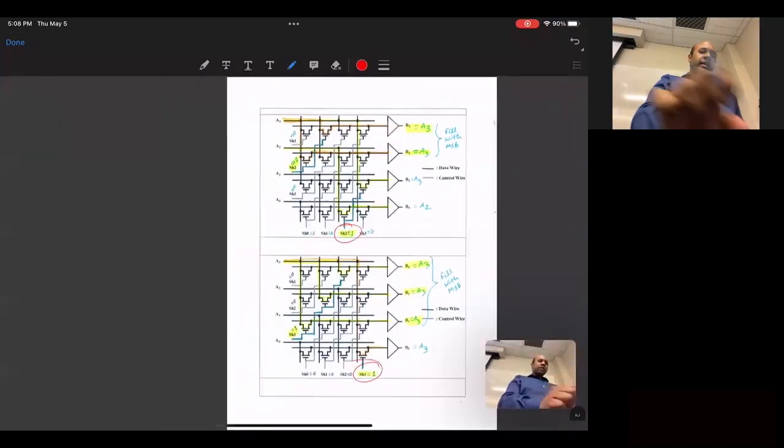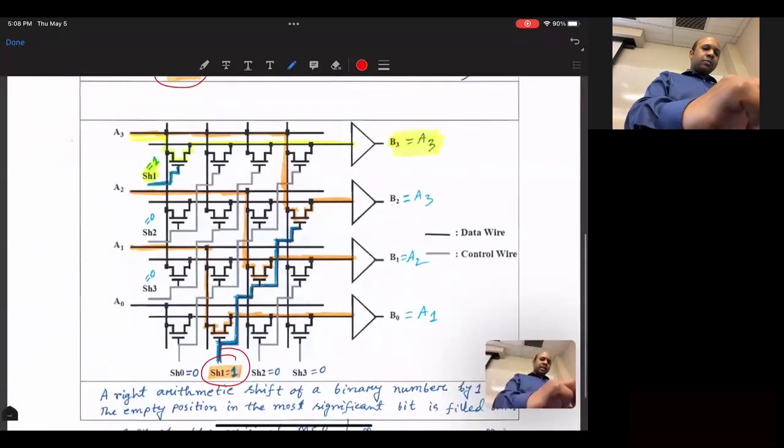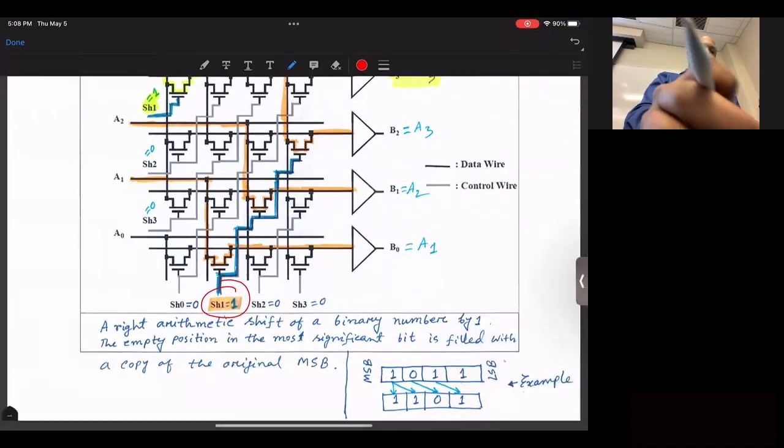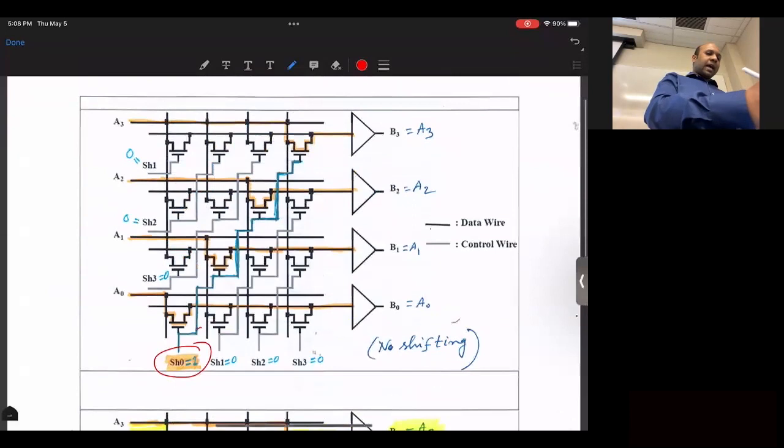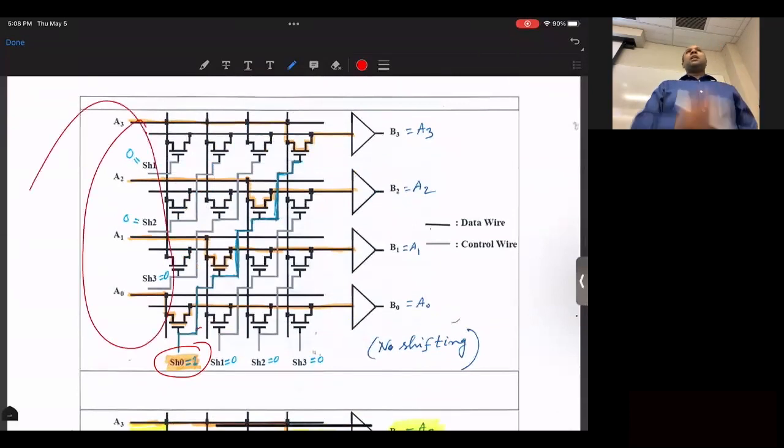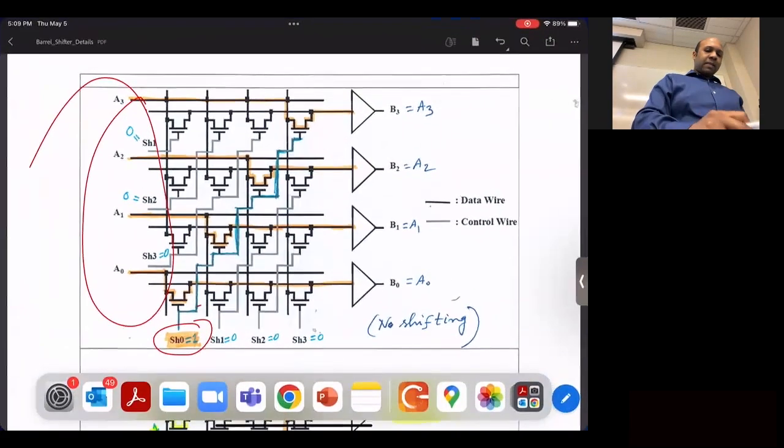It turns out the circuit that the textbook authors provided implemented a different, very specific type of shifting operation. As you see, they replaced the MSB with the MSB as well, instead of replacing it with 0. That's why the circuit was a little bit weird along this side, along the column. But I hope when you go through this, it will make sense. If it doesn't, please let me know. I'll be happy to go over it again. Okay, now let's get back to the lecture.